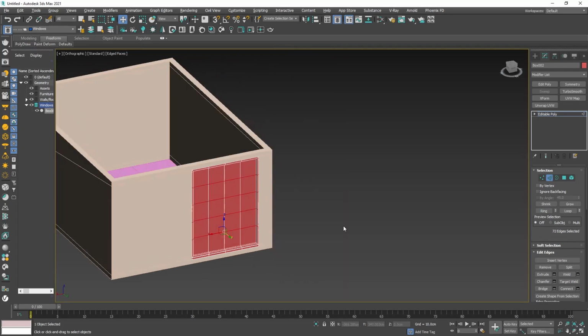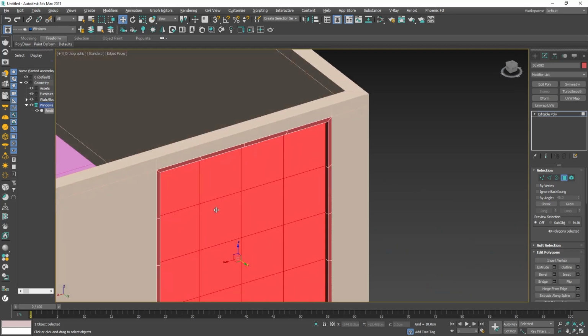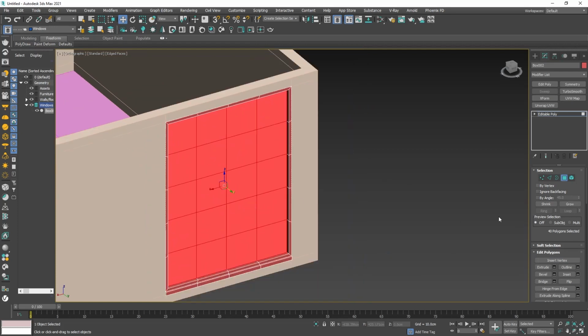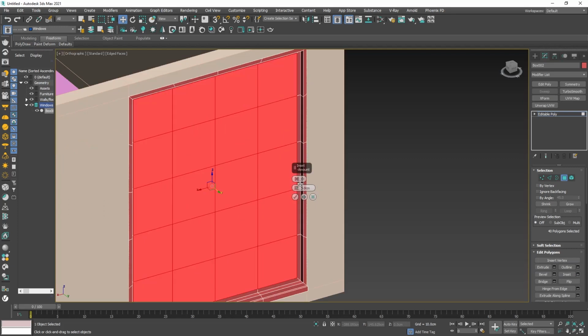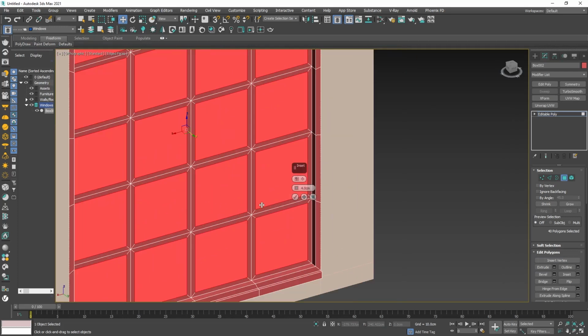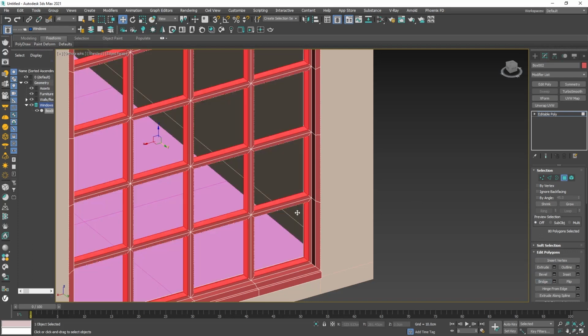Once the face is separated, switch again to polygons. You will notice that the previous selection is still active, although we separated it. To form the inner frames, here I will use the inset option again, but offsetting all the faces as one. To inset them separately, choose Inset by Polygons. Here I will type 3 cm, thinking that this will be enough. Bridge them. Okay, now we have the frames.